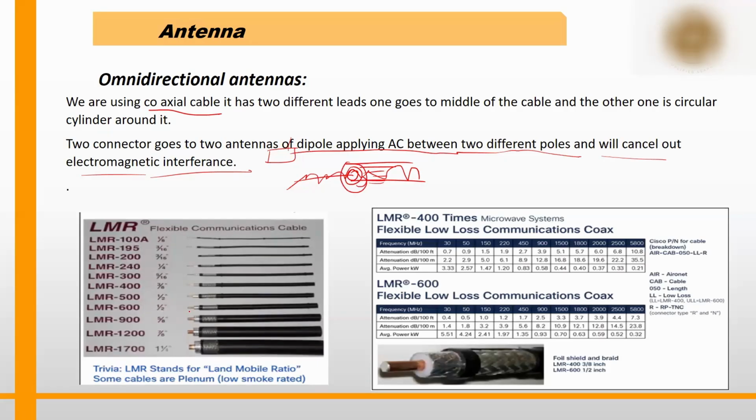Okay, you can see here copper wires, in that there is one shield, then there is a thick shield outside that. Yeah, this one is a clear picture here. Okay, and these cables will have attenuation. So the transmitter is going to generate the AC signal and send it on the copper wire. So now that copper wire will have attenuation. But this particular cable that you are using can support up to 30 megahertz. 30 megahertz signal it will support.